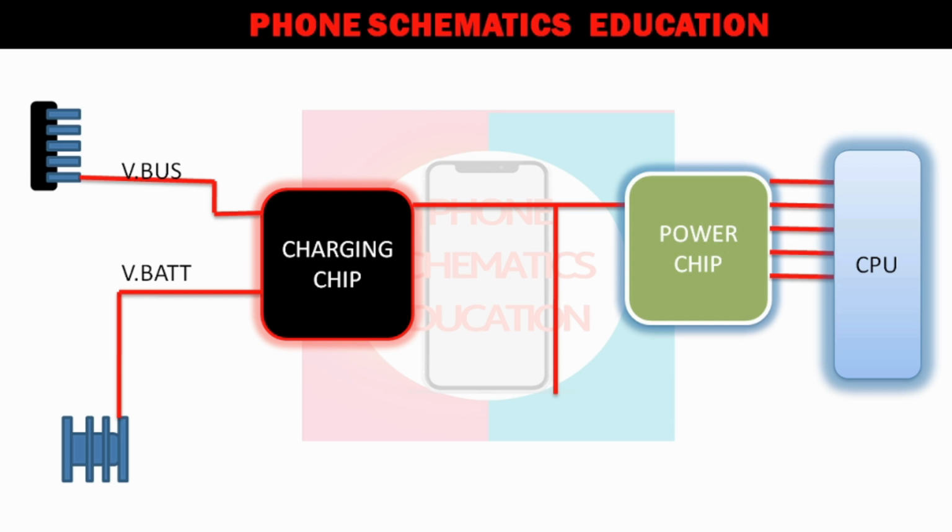You will get good information, a good detail about how mobile phone circuits work. Let's start with this. When you connect a charger, a line goes to the DC to DC IC, or our charging IC, right? We call it the V pass line.